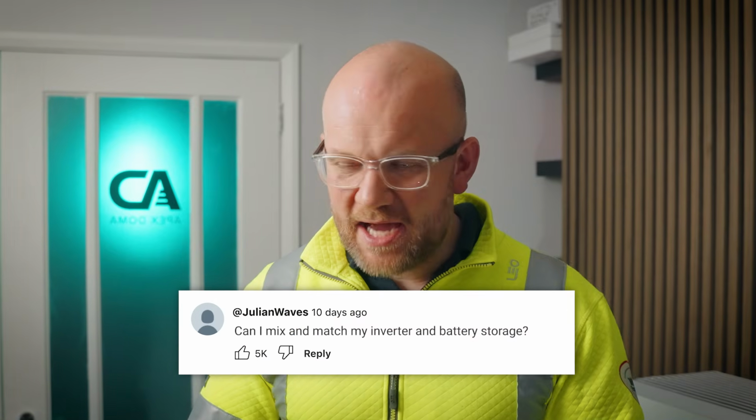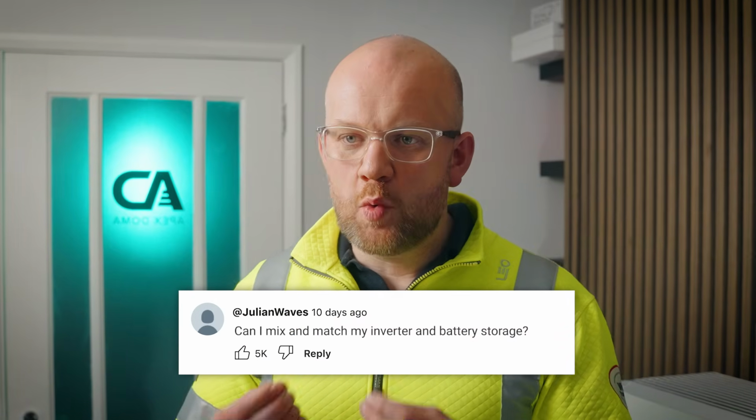Can I add any battery with any inverter? Well, first of all, the only inverters that will work with battery storage are a hybrid or an all-in-one, one battery and inverter all formed together. Mixing and matching inverters and batteries, in my professional opinion, is never wise. Why? Because if the battery fails, the inverter manufacturer will blame the battery manufacturer, who will blame the inverter. We're just prone to way more problems when it comes to aftercare of these systems.